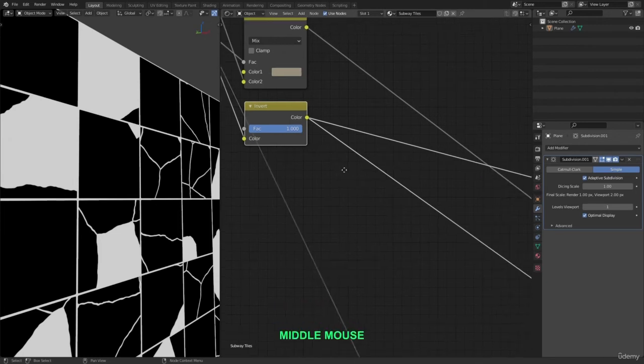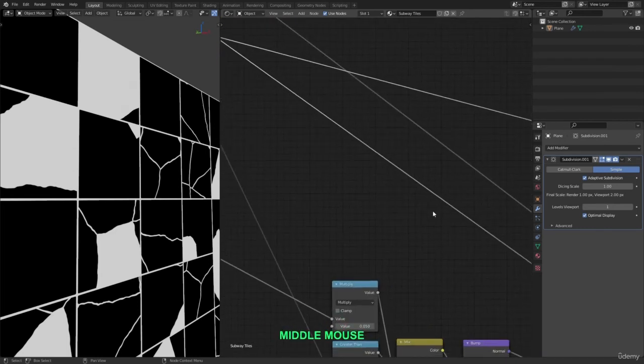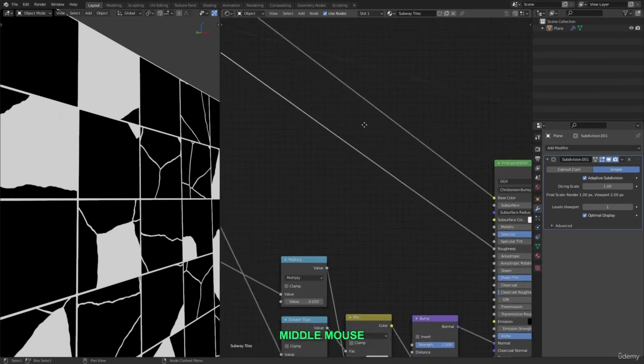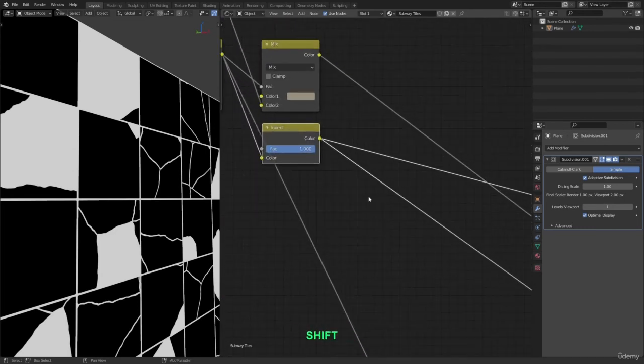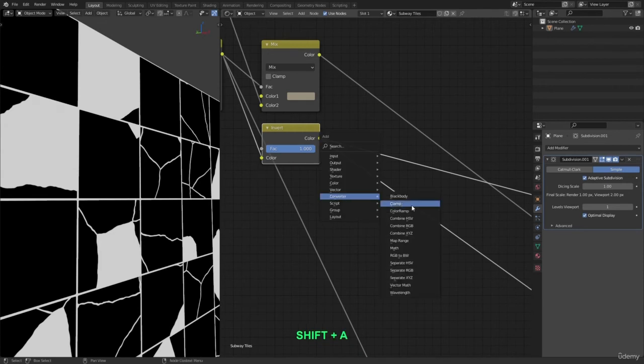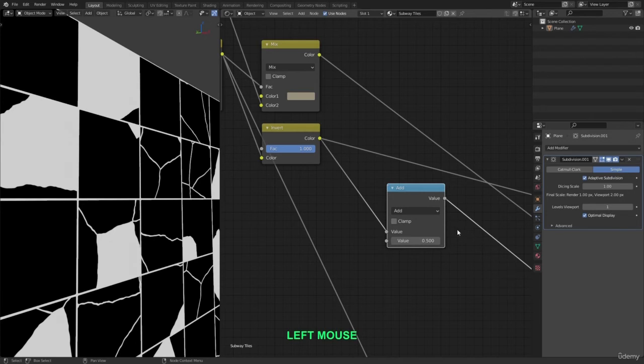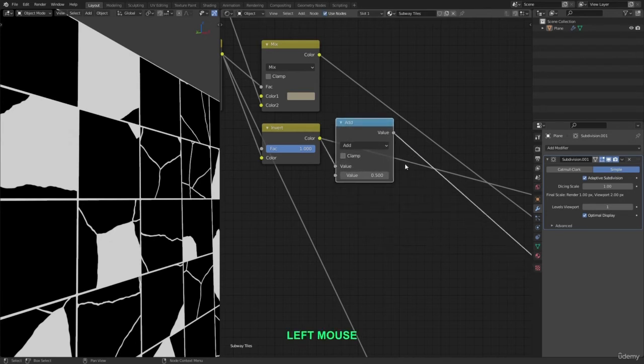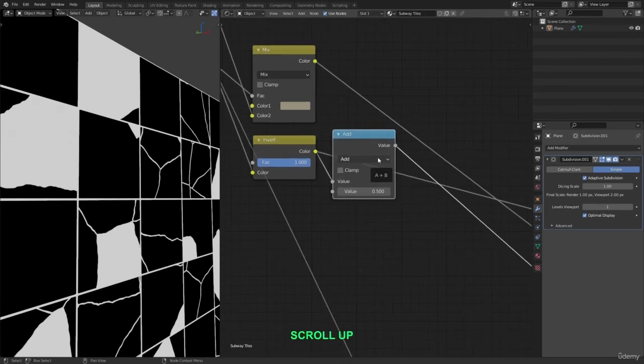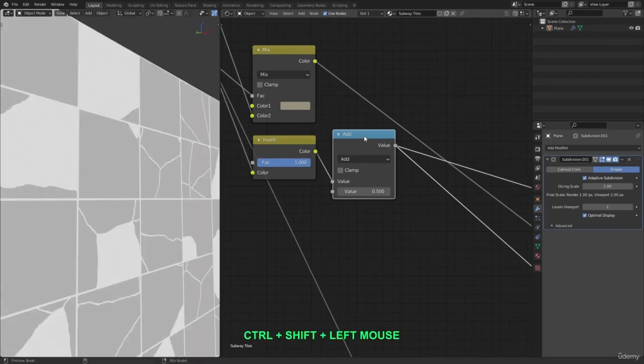And we'll add the math node in along this connection line before it reaches the roughness input. So let's press Shift and A, and from the converter menu, add a math node and drop it on this line so it connects. And then I'll press G and move that up next to it to organize. And now let's hold Control, Shift, and left click on this to preview it. And we'll leave this set to add so that it adds brightness, and you can see it working already.